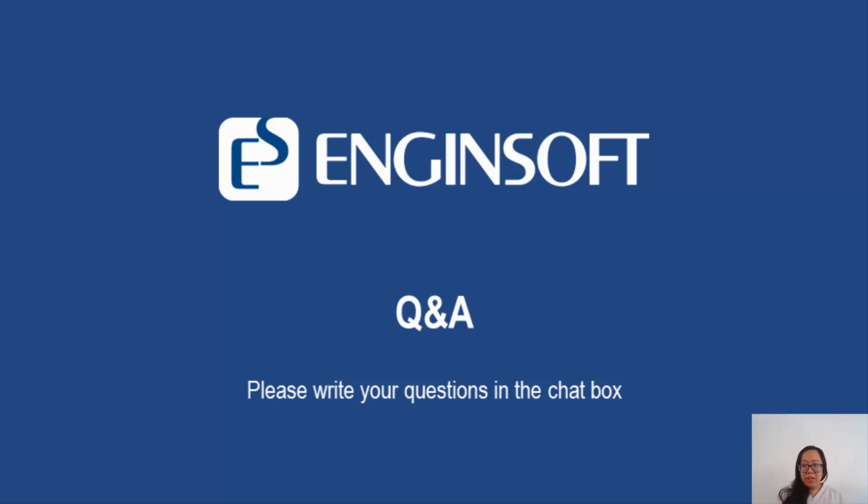Another question, one that we actually get asked quite a lot. How are GD&T and tolerance analysis different? Yes, I did mention both during the course of the webinar. GD&T or ISO GPS are our part specifications. They specify the variation that is permissible on a specific part in our manufacturing process, how much variation is allowed. With tolerance analysis, we want to take that variation as an input to our analysis and understand the outputs that we'll have across our assembly.